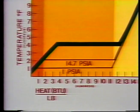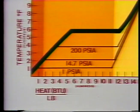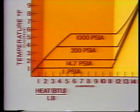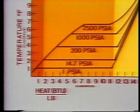Again, the process line is similar to what we've seen before. Let's look at two other pressures. Here's the process line for 1,000 PSIA. Here's the line for 2,500 PSIA. Notice that the process lines for all of the pressures that we've looked at are similar. The major difference between them is the saturation temperature and the size of the transition zone.